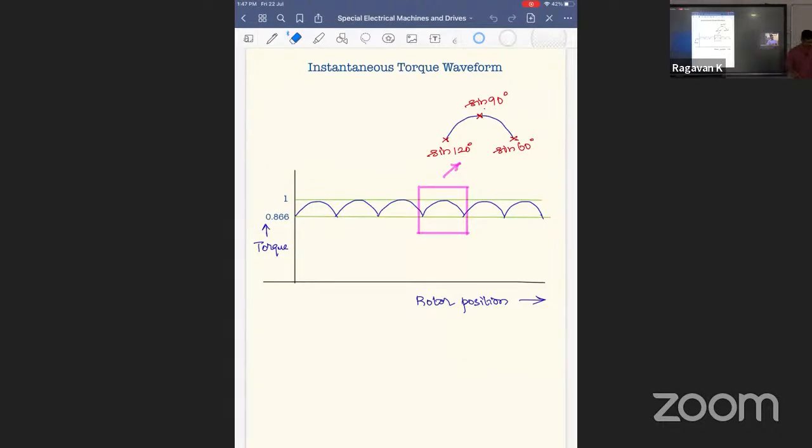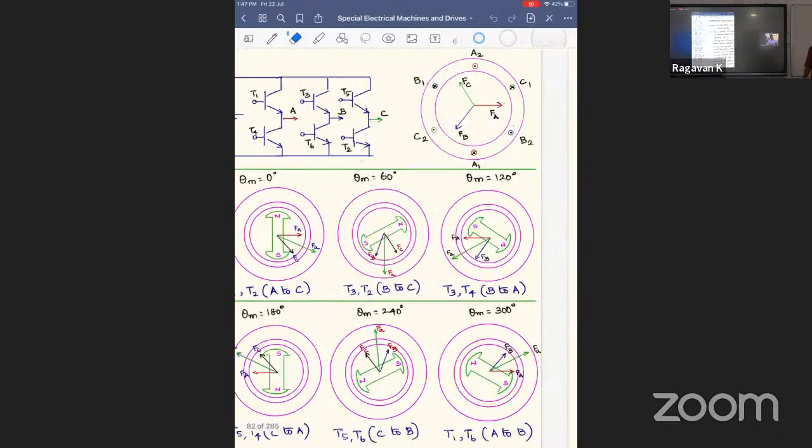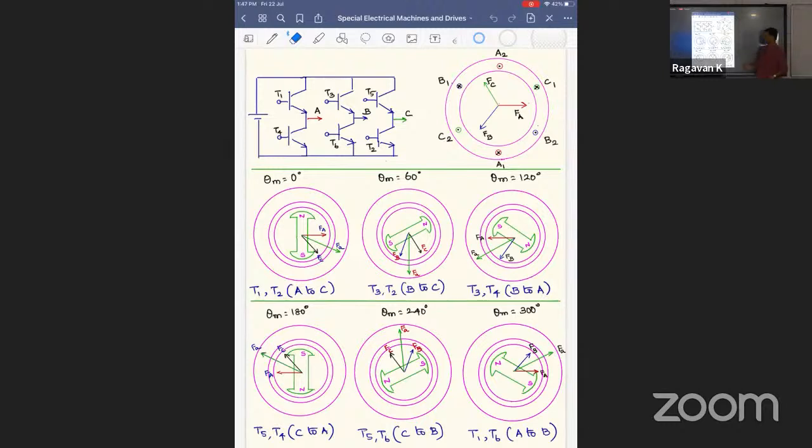All right. So whatever I had explained earlier, I will repeat now. FA is here and FC is here. The MMF vector due to energizing two phases at a time, this is the resultant. Now you forget about the individual MMF vectors. This is the resultant. And FF is this one. FF is south to north. It's pointing like this, and FA is like this. So the initial angle is 120 degree. Now the south-north pole rotates in the clockwise direction.